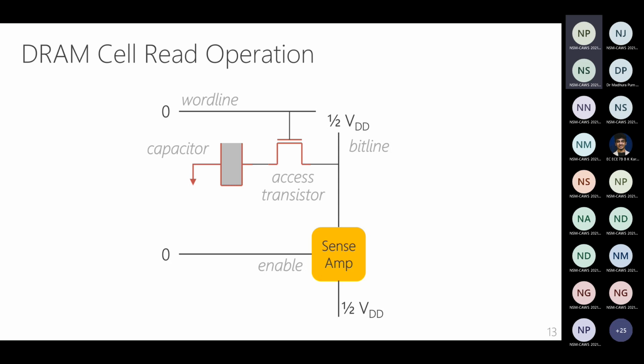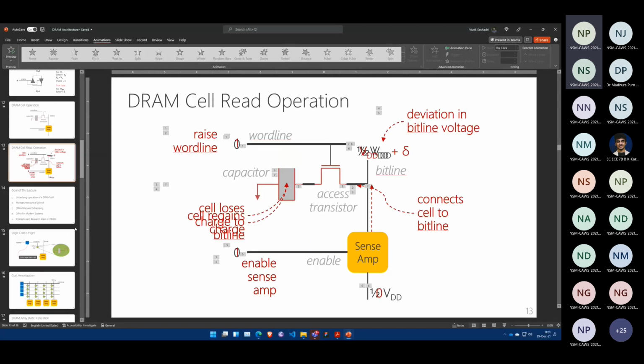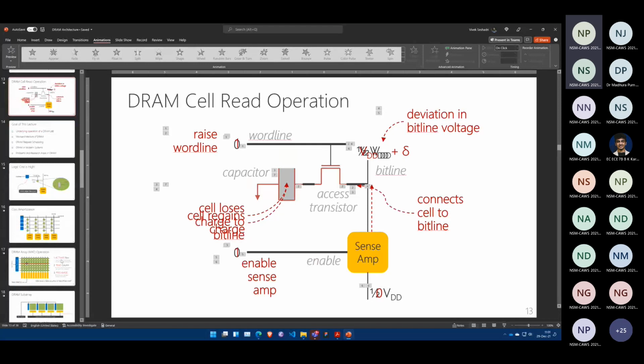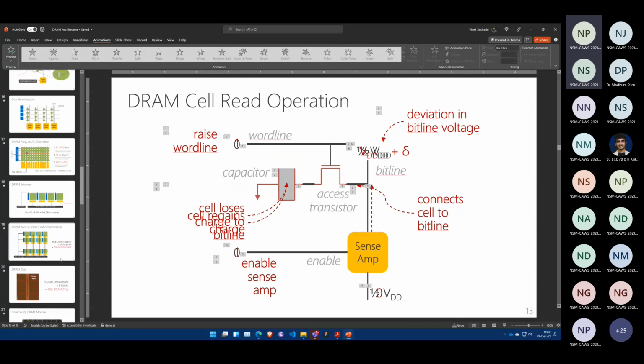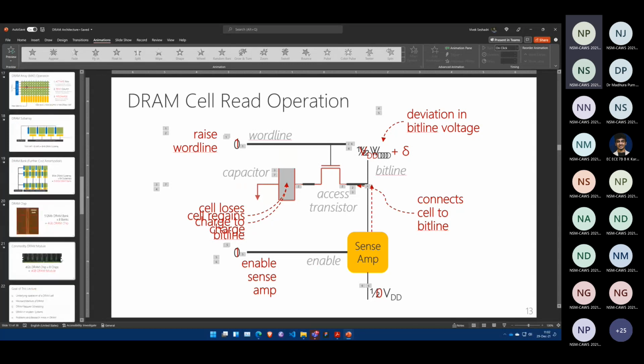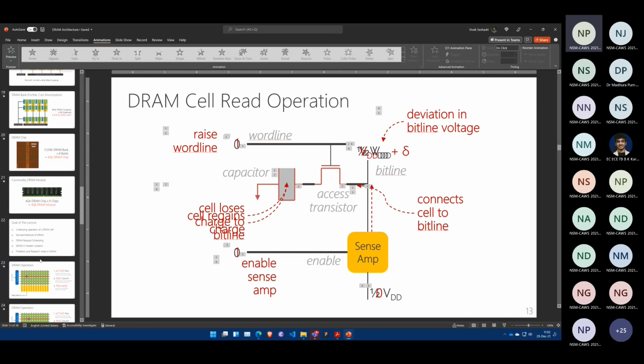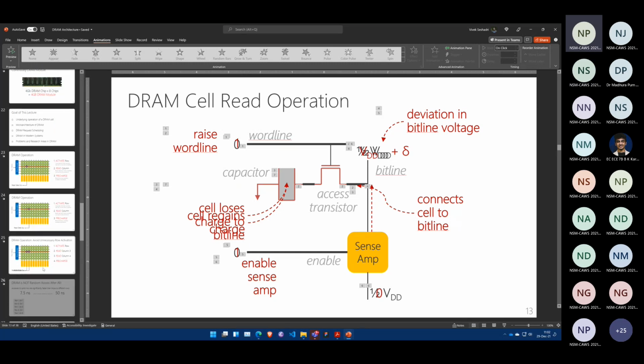Latency also increases when you increase the bit line length. Yeah, absolutely. So latency increases when we increase the bit line length, which is one of the reasons for maintaining it at whatever, like this 1024 cross 1024. Right. Reliability is one aspect, latency is the other aspect. Actually, if time permits, I'll take you through a couple of ideas that arise out of the understanding of this DRAM operation.